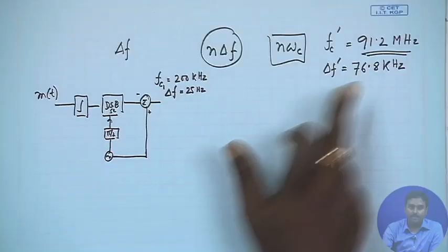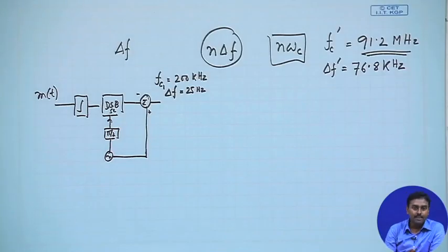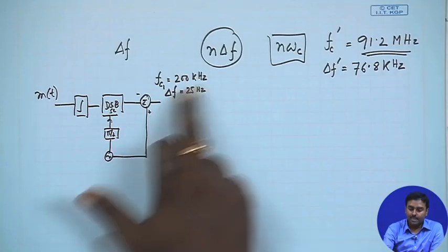Okay. So, that is 76.8 kilohertz, and overall bandwidth will be double of that, okay. Because at that frequency the actual voice bandwidth will be much smaller. So, with Carson's formula you can put it in and you will get almost a similar thing, around 150 kilohertz of bandwidth. Okay. So, from this del f to this, immediately what I will be trying, probably that means I need a multiplication.